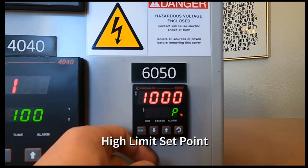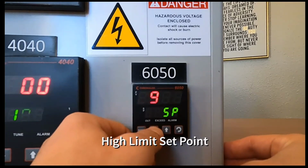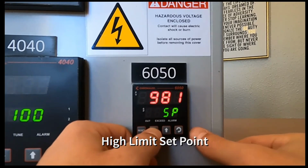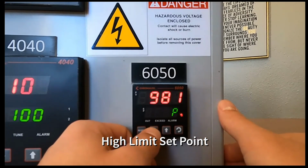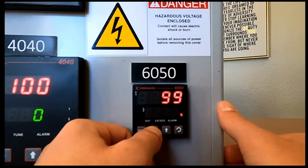Vince, also to point out, the reason that's 1,000 is you set your limit in the configuration mode. It defaulted to 1,000. Yes, and since we had the control set to a high limit, it's going to take the upper limit that we set, which is 1,000. If you had it on a low limit type of alarm, it would default to the 0 that we set.